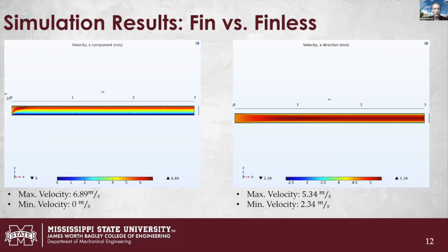But you also may notice that there's a much bigger band of zero velocity, or very low velocity for that matter. It might not be zero, but it's very low. So this is also a concern for us with corrosion inside the pipe, because there's no fluid flow in there. It is causing some buildup, and they potentially have some problems in our system.